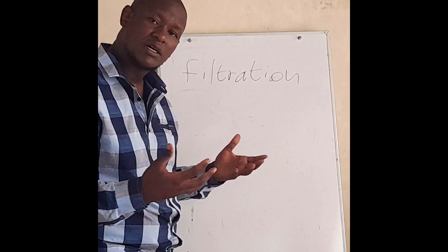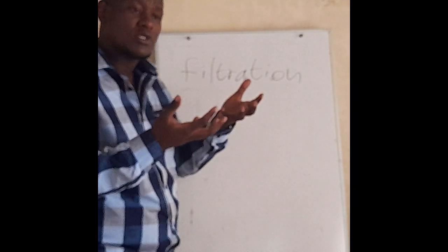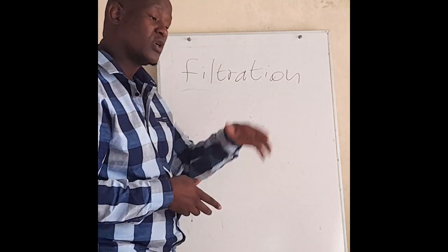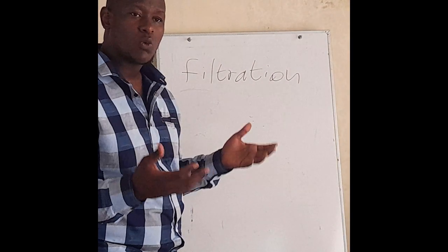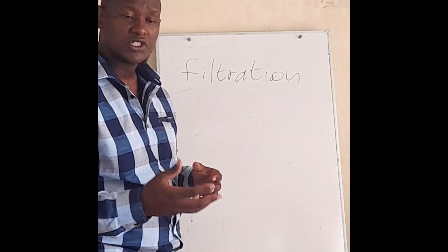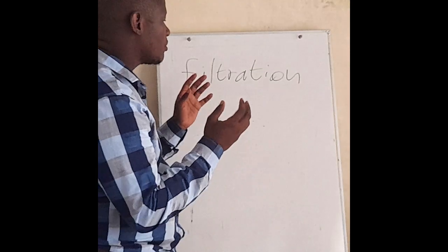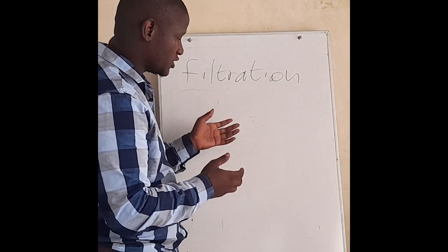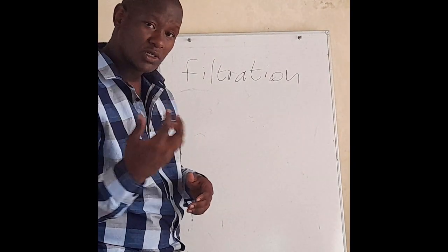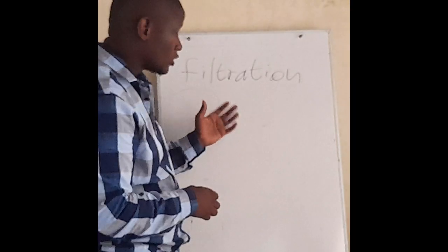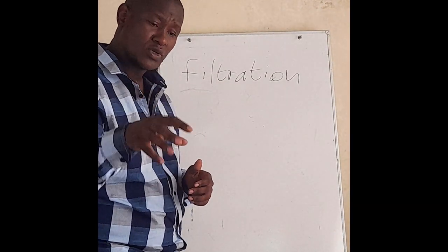because remember this is a filter. What is its main purpose? The main purpose of it is basically to filter out solid particles that weren't able to settle down under sedimentation. So that's one of the purposes and functions of it, and it's one of the most important stages, because if solids are not filtered out properly, those solids will tend to go to the disinfection, and we'll tell you more about that when we get to it.